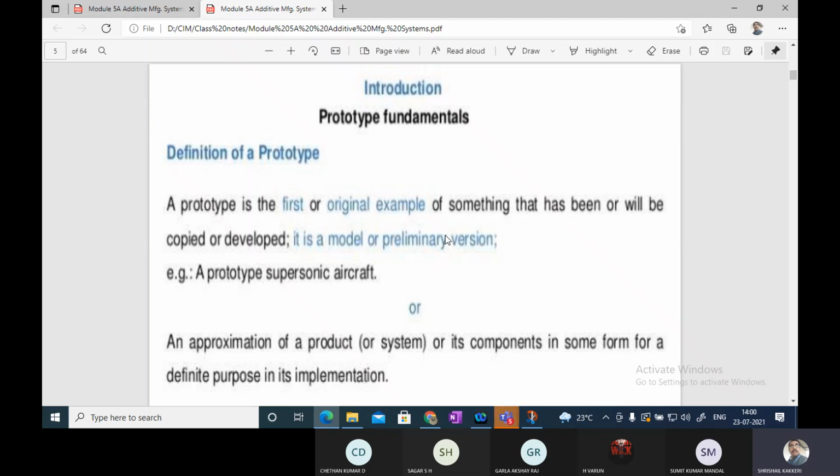You can see that in CNC motions, we have 3 types: PTP, point to point, a straight cut, and contouring. The contouring requires more than 2 degrees of freedom of motion in machining. Correct? The tool will not be moving along only the X or Y or Z axis, but will be taking the reference of all 3 axes at a time. Due to this, we get a very, very complicated shape.